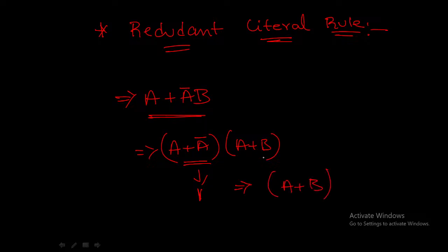So what is the redundant term we are removing? It is nothing but A bar. So this is the redundant literal rule. We can remove the redundant literal which is present here. By using the distributive law, we are able to remove the particular redundant literal.